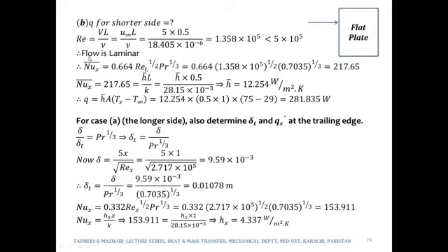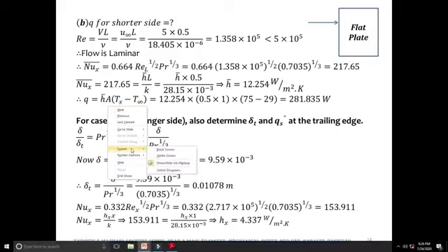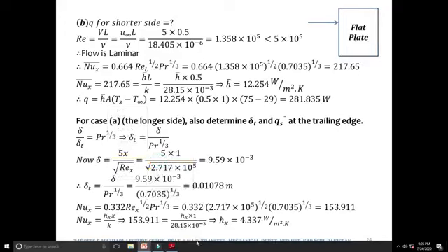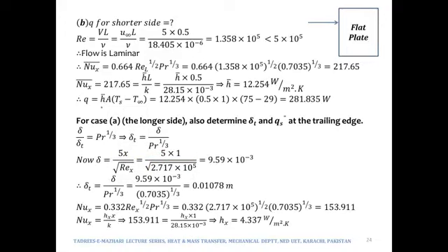Now again, since we need to find out the total heat transfer, it would be found using h bar A delta T, and in order to use this equation we know all the parameters except h bar. So h bar would be calculated using this expression of Nusselt number, for which we must know Nusselt number in advance. So since we need to know the Nusselt number prior to using this expression, we would be calculating Nusselt number using one of the expressions of Nusselt number.